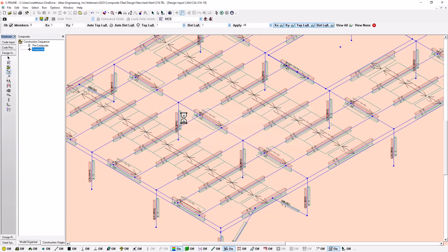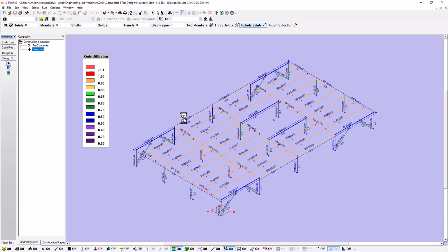And S-Steel is running through the design of these members according to those design groups that we'd set up. And you can see here it's giving us utilization ratios and cross-section sizes. And this may just remind you of the different cross-section design groups that we set up, or member design groups rather. So we have our depth-restricted beams here, which are using a W410 section. Then we have next to that a bay that's using our standard joist cross-sections, which are W460. And you can see the utilizations in each. They're about utilization ratio or demand capacity ratio of 1. Some of them are different. Again, if they are part of the same design group as their neighbors, they will have perhaps over-designed utilizations if they are part of a group that is contained with a higher stress section.